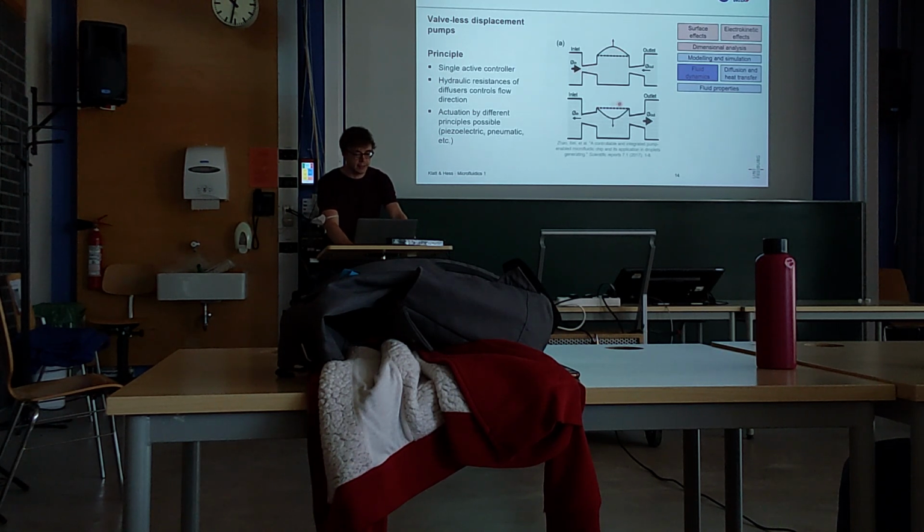You have one controlling element that can be deflected, and that increases or decreases the volume in the cavity. But thanks to this preferential flow direction, there is a bigger inflow from the inlet side and a bigger outflow to the outlet side.